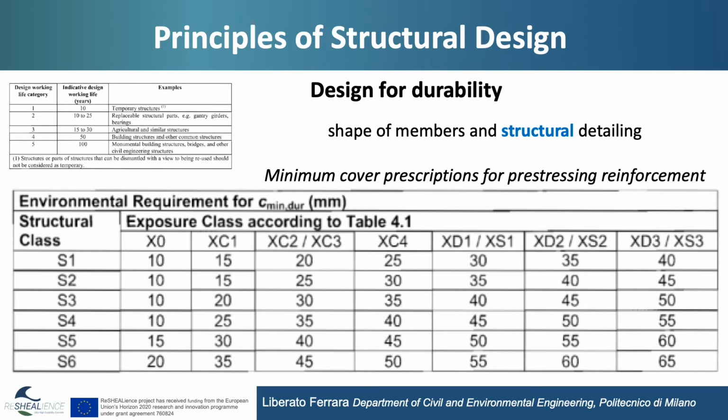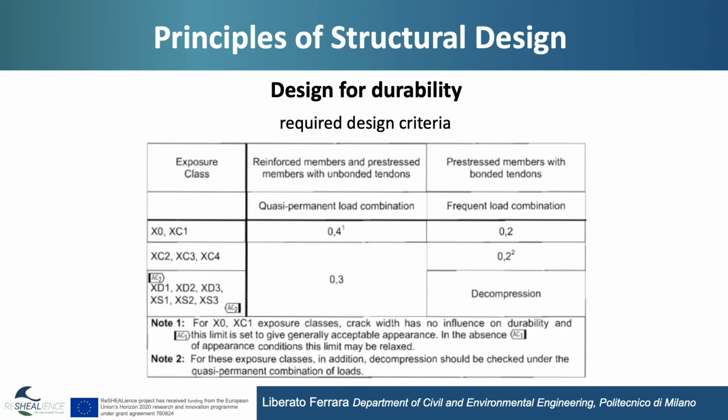And as a matter of fact, these are structural requirements. Like structural requirements are those which, for the different exposure classes, for the type of reinforcement, and for the combination of actions, we are given with reference to the opening of the crack that we have to calculate, or even to look for a decompression serviceability limit state under the frequent load combination, for example, in the case of quite severe exposure conditions, like when we have high risk of corrosion from chlorides, whether they are not or from seawater, class XD and class XS.